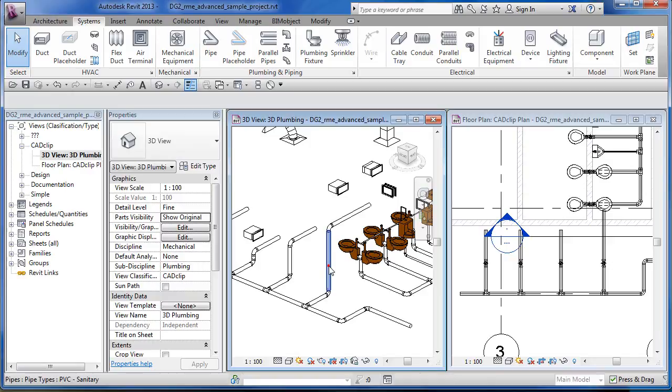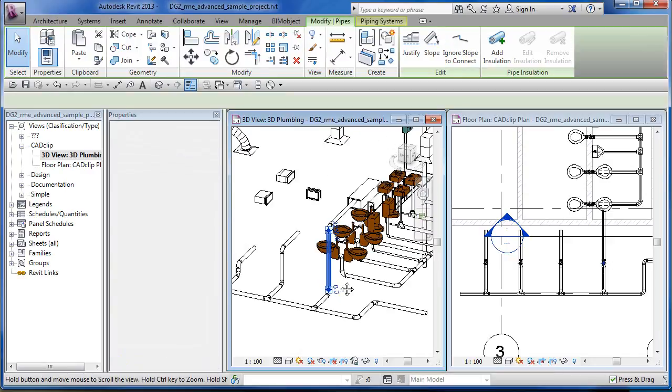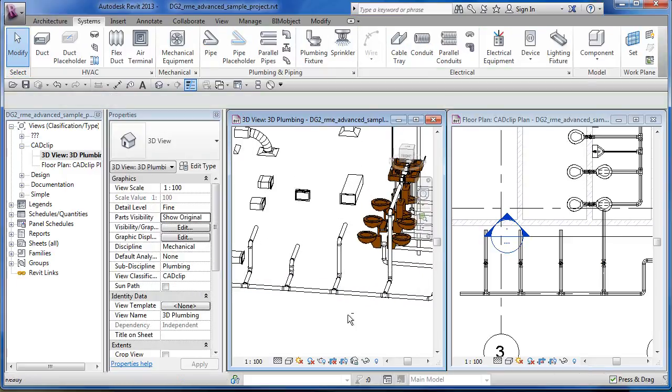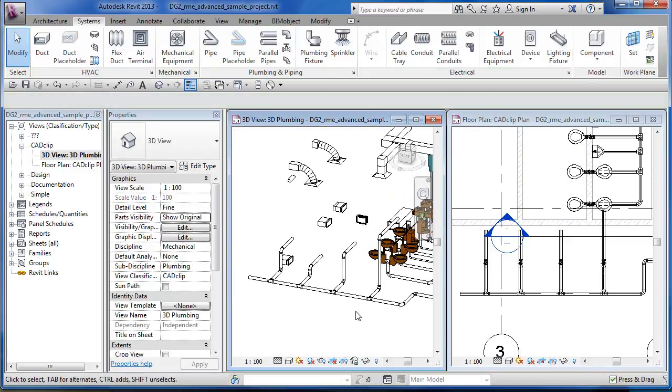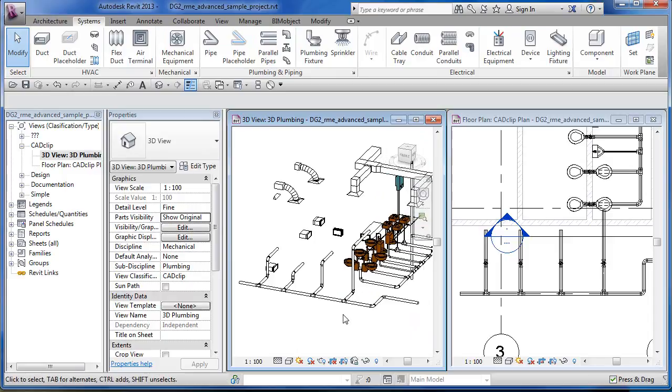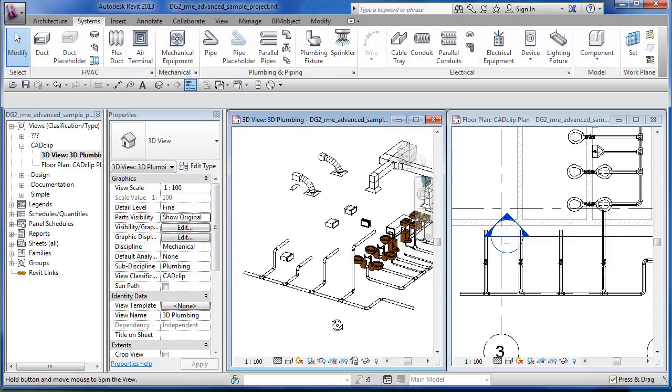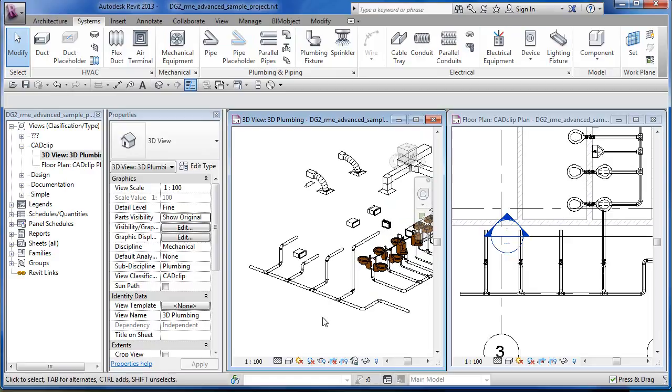So I've altered those pipes a little bit, but at this point they're all pretty much flat. Okay, so now maybe we want to add in a little bit of slope to that. So then this is what you do. This is what's nice in piping: you can take this as a kind of system or a group of pipes and then add a sloping system.